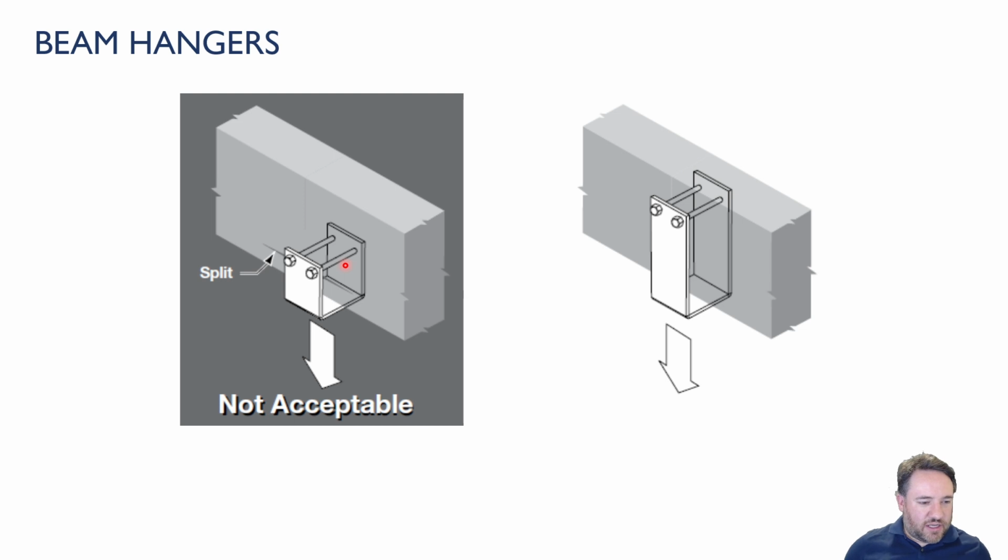Okay, now what about hanging something from a beam? You might certainly have some occasion to hang things from beams at some point. Now, you might be tempted to do something like this. Neither of these is really the ideal detail for this, but let's say that I did want to bolt into the side of a member in order to hang something from it. So I have a bolt through here, and I'm basically hanging from that bolt. I have something structural hanging down from below, say I'm picking up a walkway or something.